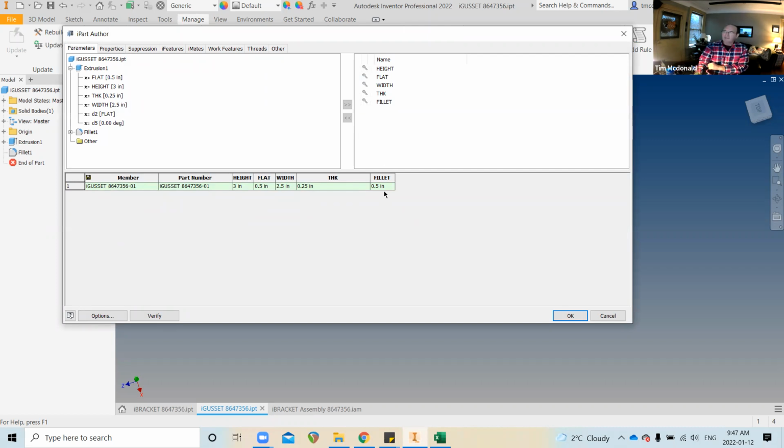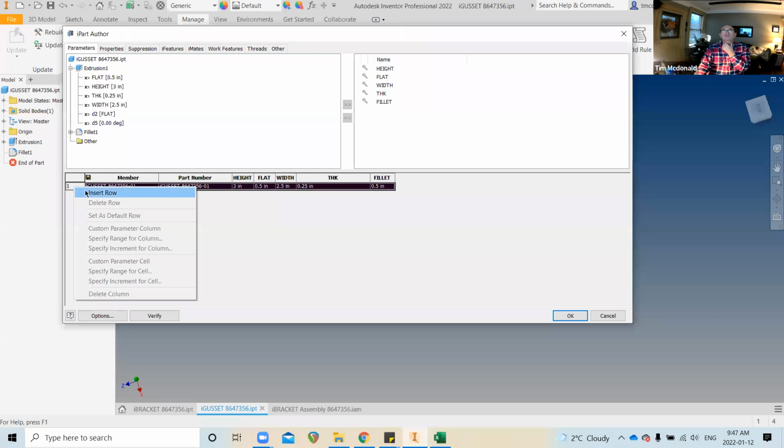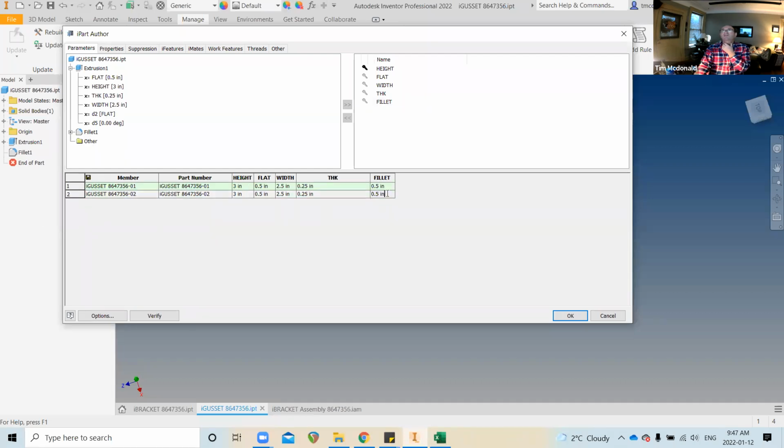I'm really not certain about the size of that. I know that the size of the fillet on the second one is going to be different because the plate thickness changed and we changed it to 1/2 inch and the bend radius is twice that. So I need this to be 1 in the second iteration. I think I'll change the thickness of this gusset. And this is not a sheet metal component, so I can just change it to whatever I want. 375, which is 3/8 plate. Because this bracket, the one it's going on, the second iteration assembly will be a 1/2 inch bracket.